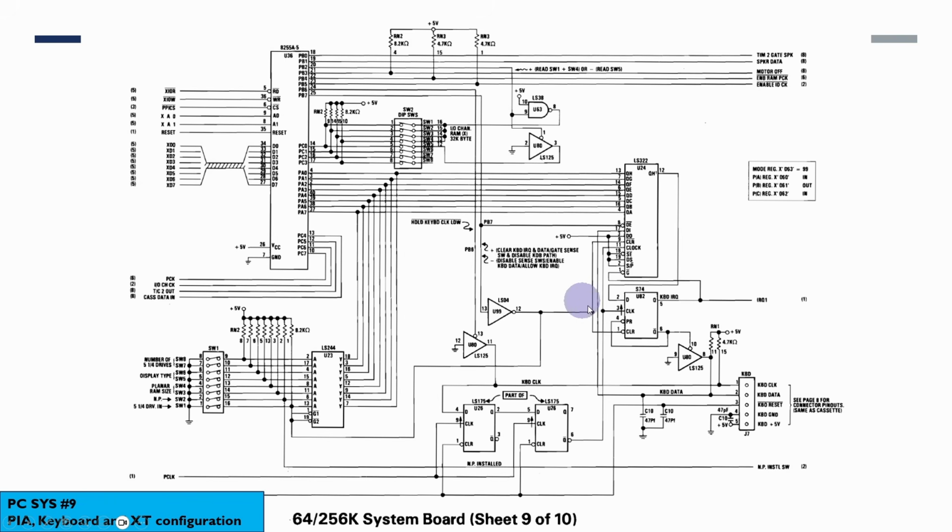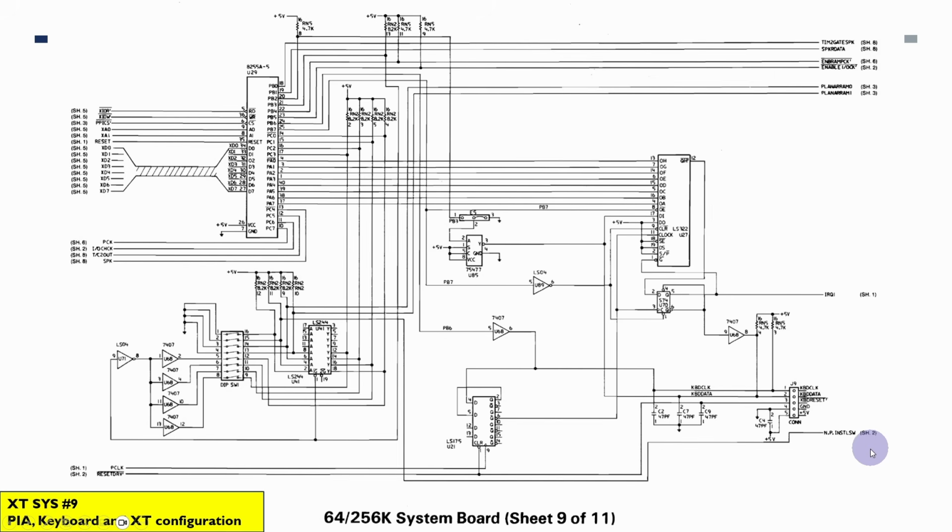And so this is very much a hardwired keyboard interface, and this was replaced in later versions with the Intel 8042 microcontroller. And in fact, in the Breadboard PC and XI8088 designs, there is a PS2 compatible keyboard controller that we use. And again, you'll see here very similar. Some of the dip selections will be slightly different, but pretty much the rest of it is the same.